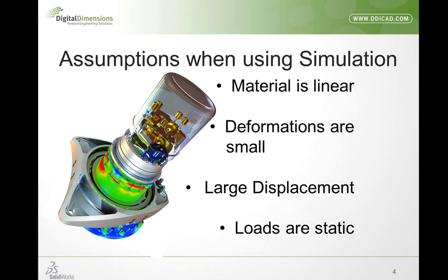The next assumption we're going to make is that our deformations are small. Now we have to make this assumption because of the equations we're running. We're using a set of equations, and the assumption is that all of our deformations are small. Now that's pretty subjective, right? It depends on your application, the scaling of your models when you're going to run the analysis or model your designs.